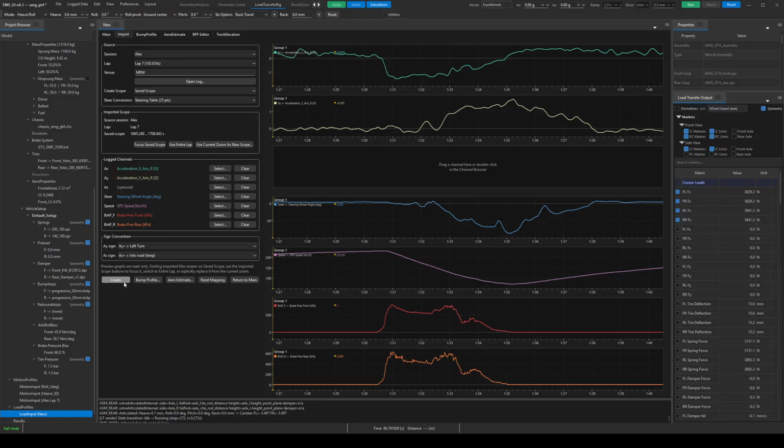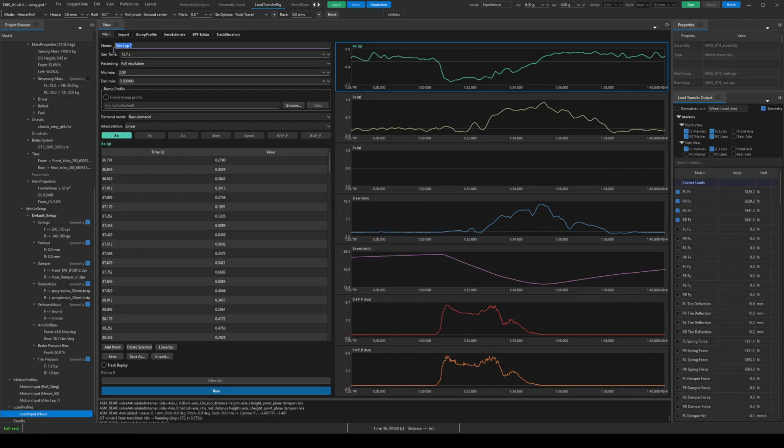The setup change affects the simulated tire loads and suspension response, but it does not feed back into the original logged chassis accelerations. The acceleration history is treated as an imposed input. So this is not a full closed-loop vehicle simulation.